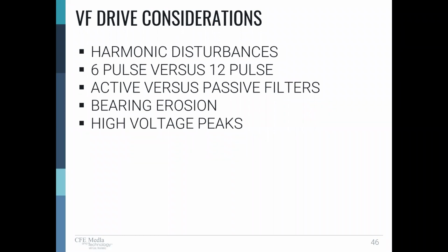But we're trying to save money here and not utilize extra construction cost. We're trying to save operating cost, and we've shown that you really can't save the operating cost with VFDs if there's any way to reduce the static pressure in the ductwork.